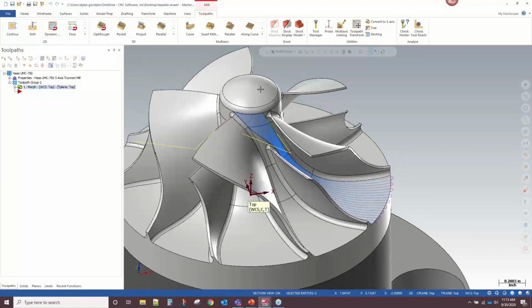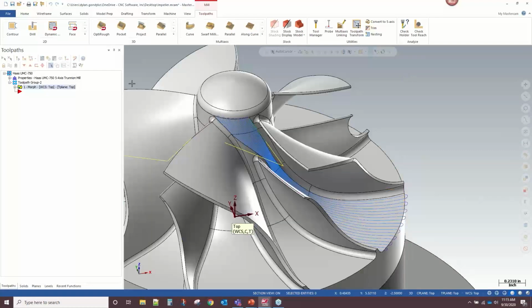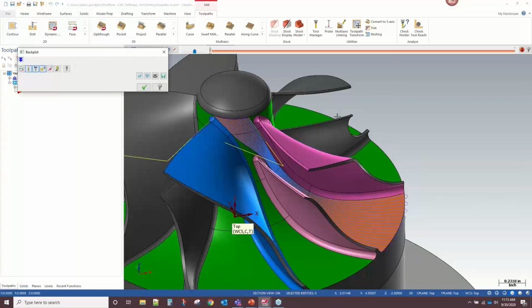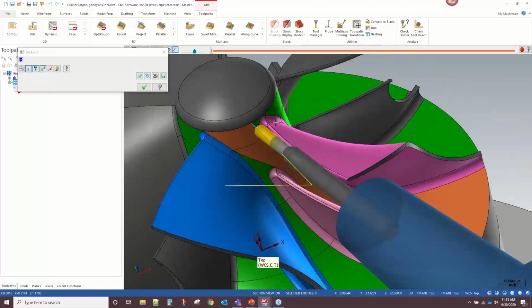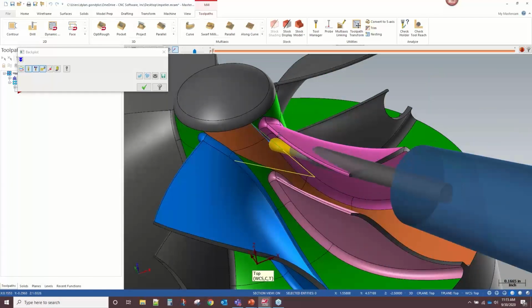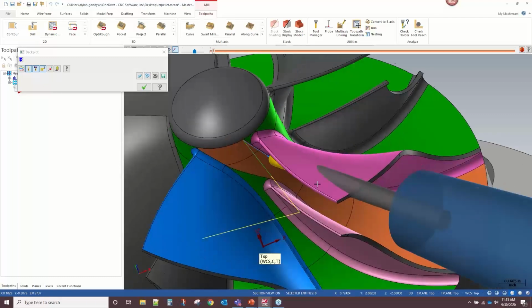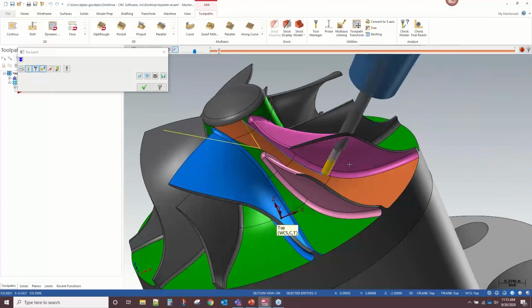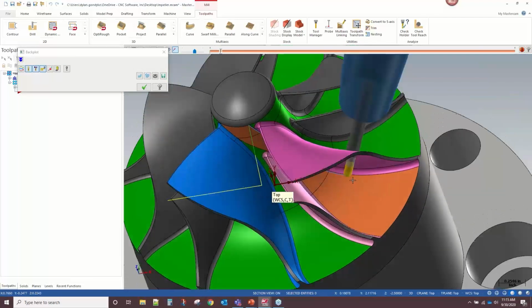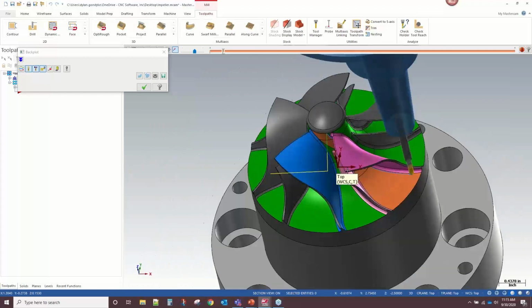And what I'm doing for tool axis control is I'm pointing the tool based on the surface normal vector. So this is kind of the result that we get. So we're staying normal to the orange surface. And you can see because of that, we immediately have issues going through the throat area of the impeller, right? We're massively colliding here. And we've got that collision almost all the way down to the end of the orange surfaces.